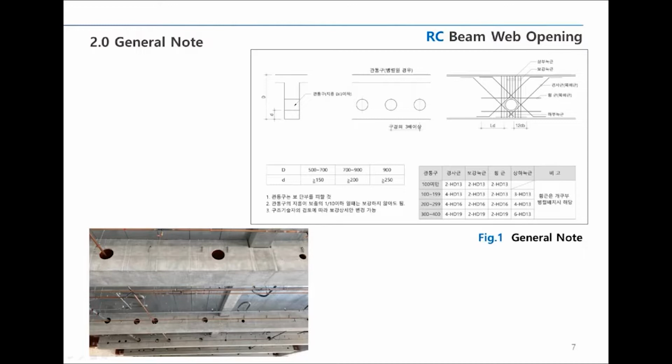An appropriate concrete gap normally means under 1/3 of the concrete beam depth. In other words, if the depth of the beam is 600 millimeters, the maximum size of the opening is 200 millimeters.